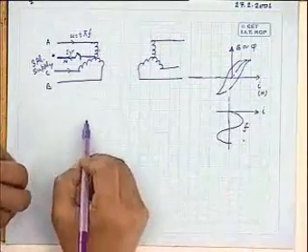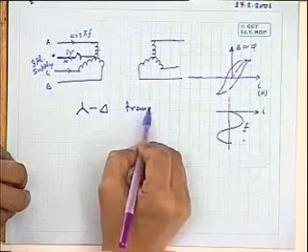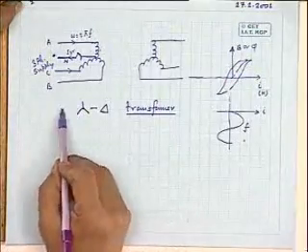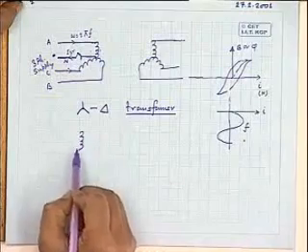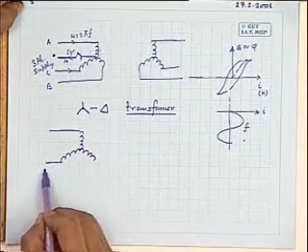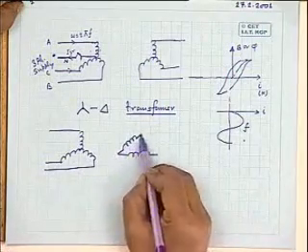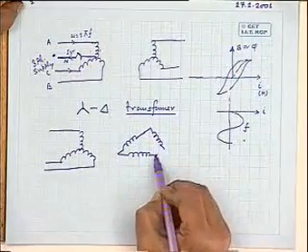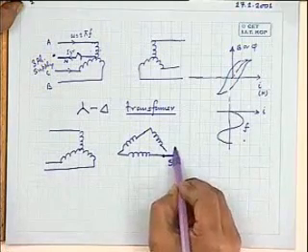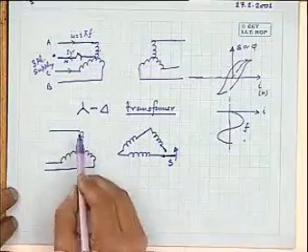This you just try to understand. Consider a star-delta connected transformer, with neutral not connected, and the connection will be like this. The primary is star. Of course, these terminals will not be shown. It is understood we have correctly connected it in star, and suppose this side is delta. And suppose in this delta, before completing, I have put a switch here, which if I close, will complete the delta. Let us understand what will happen.